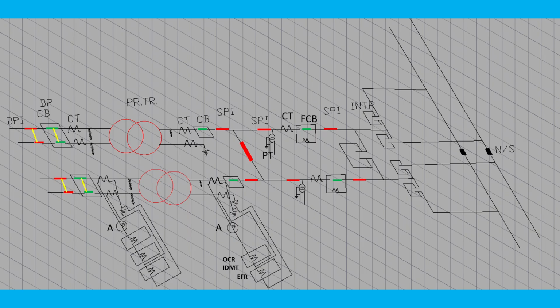It can be operated electrically and manually, but not through the relay. So if you close it during faulty condition, then your circuit breaker will trip the circuit immediately and protect our OHE.